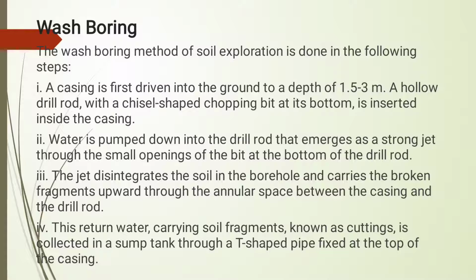So the soil gets disintegrated and the broken slurry is carried up through the space between the drilling rod and the casing. This return water is collected above the ground in a tank, and after a few minutes that water is reused for this purpose.